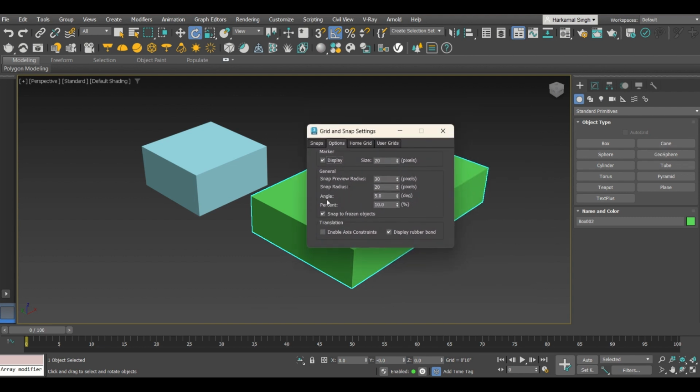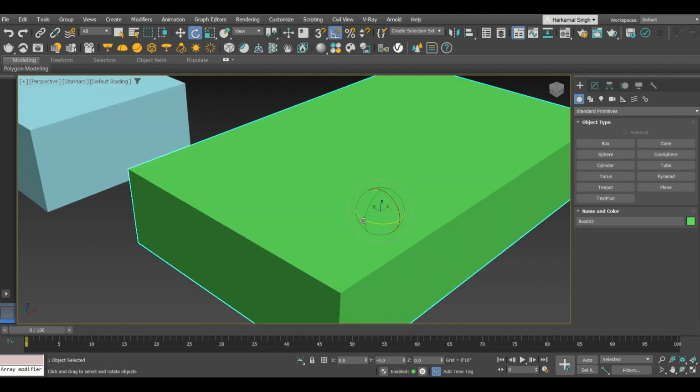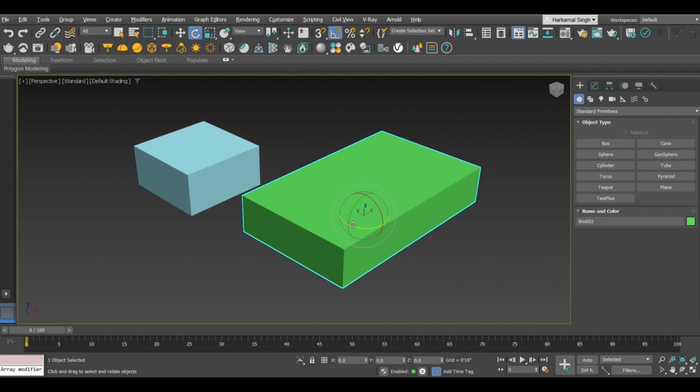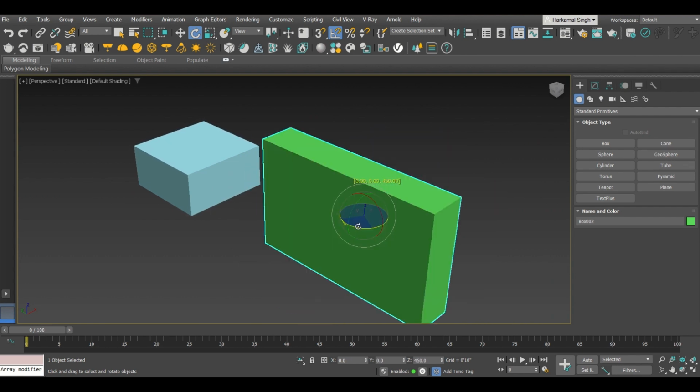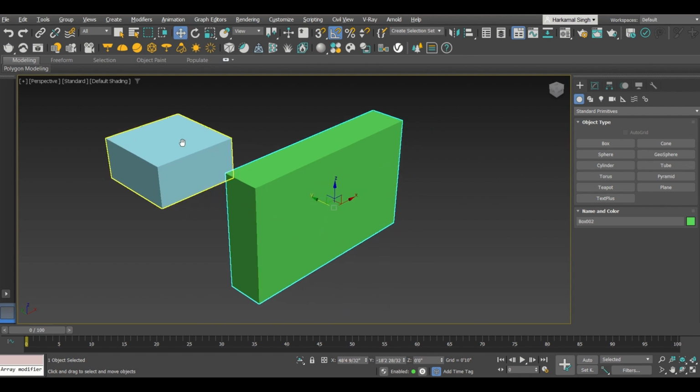Over here, in the options, angle is written. Make sure this angle is set to 90°, else you can set it as per your convenience, whatever the requirement for your modeling is. I recommend 90. Why? Because once we are in this rotate command, its least count for the angle will be 90°. So it will rotate only in 90° steps, in whatever direction you are rotating, right?